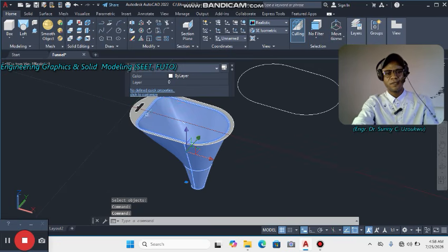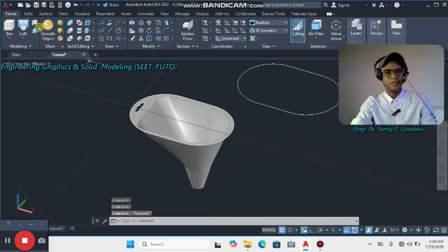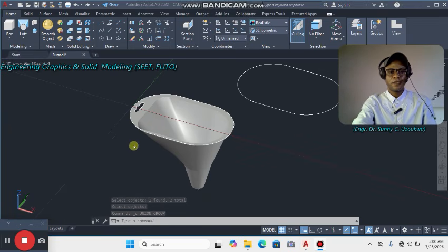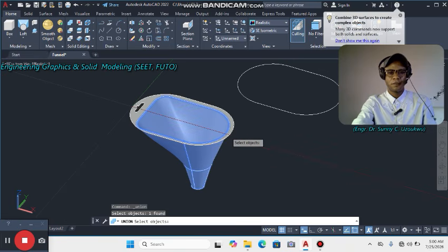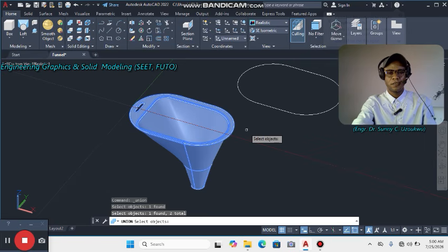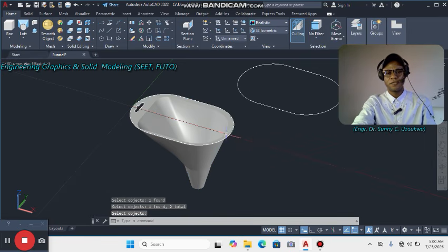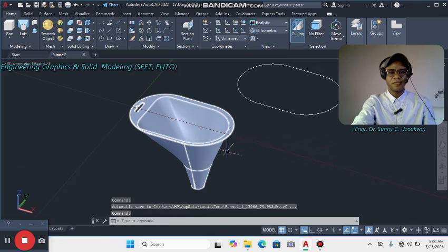Sorry, I've not really joined this to this, and that's why I have. Okay, yeah, to make it common entity, all I need to do is to click on Union. Alright. Click on solid union. Then click on this place and click on this and click on this outside space, and that gives you common entity. Now I want to add color to the entire object.